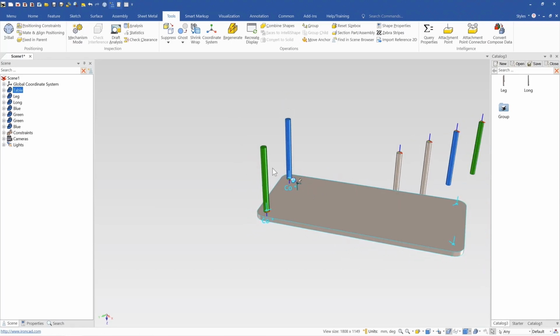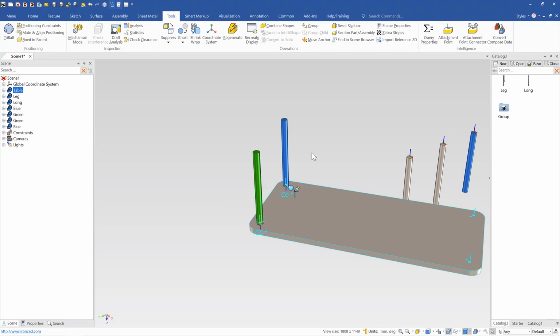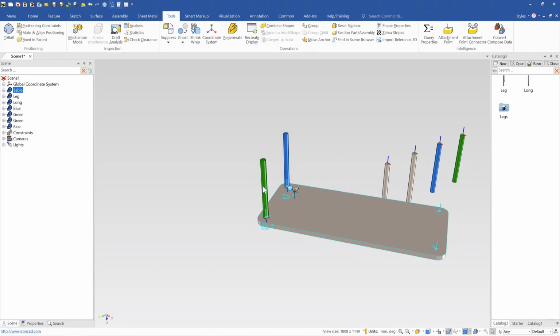So this doesn't have to just be blue and green. This could be metal leg and timber leg. This could be a certain variation of a much more complex model. This could be a type of wheel added to a vehicle, for example. Basically the attachment point on the table is requesting a variable or type of the item being dropped. So this group then becomes legs, and the actual item is requesting the type of leg which gets dropped out onto it when it's dropped from a group.